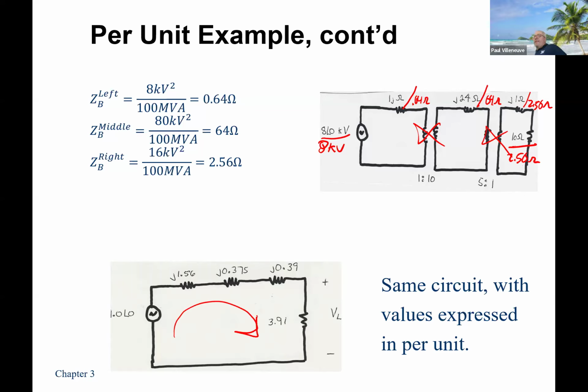Yes, sir. VB1, in the order you want, right? No. Because VB1, which is A divided by A, should always be 1. No. You said V base 1 is not equal to 1. Right. The per unit value may be 1, but it doesn't have to be. In what case can it be not? What if you said, okay, it's a 13.8 kV generator and you wanted V base to be 15 kV? Why?